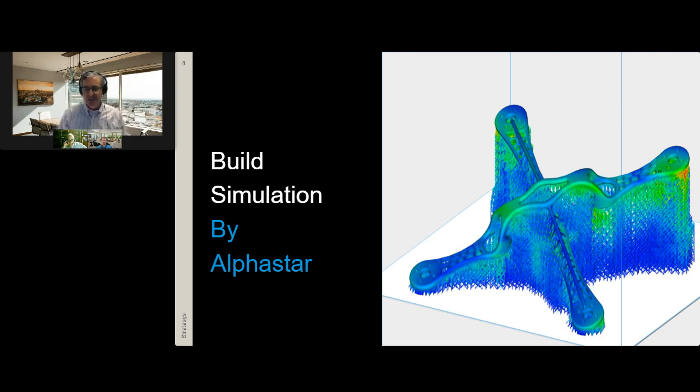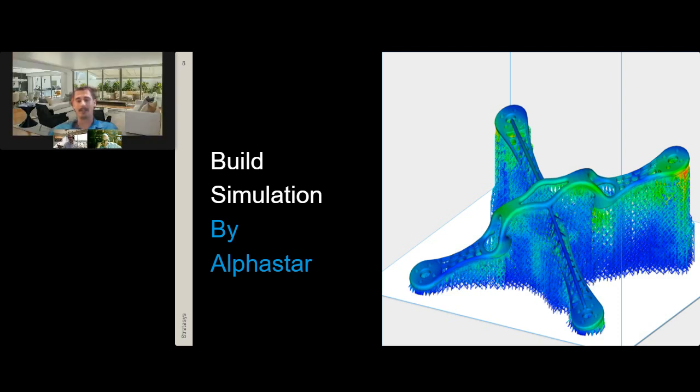Yeah. So as far as, if you're building on an F900, to an F900, yes, that scan that you used on F900 number 1 would be valid for F900 number 2, again, keeping everything else constant. Where we run into more difficulty is if you're going, say, from an F900 to an F450, where in those machines the oven characteristics are slightly different.